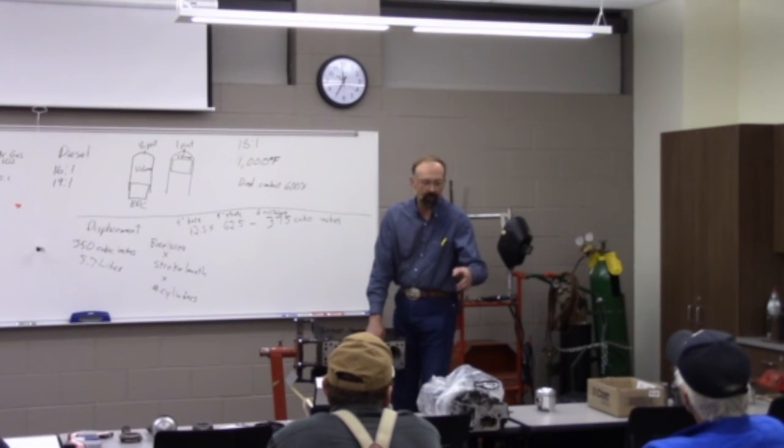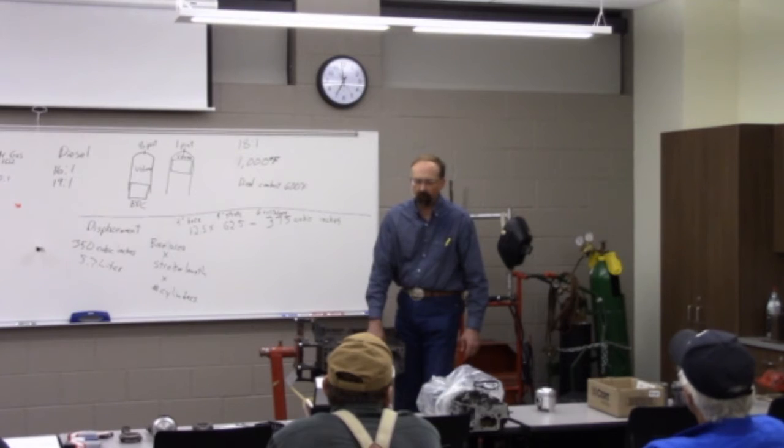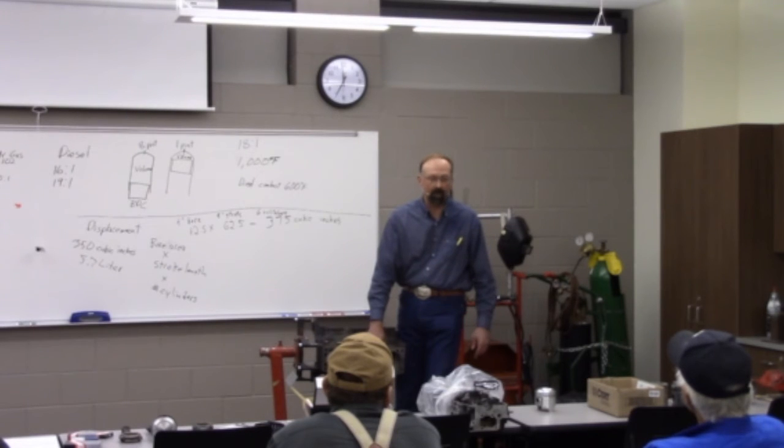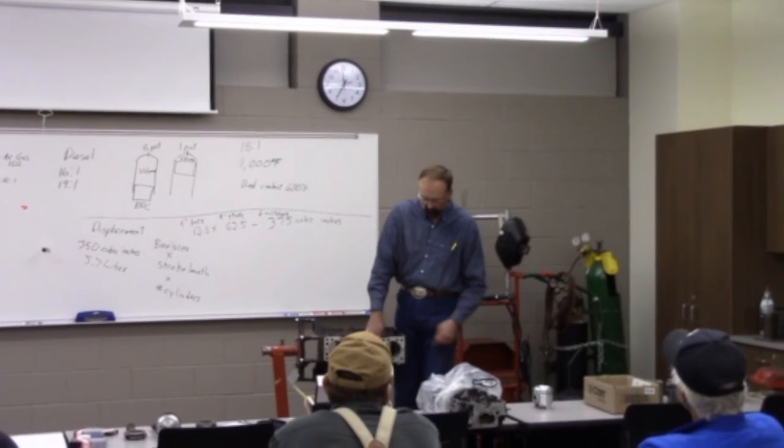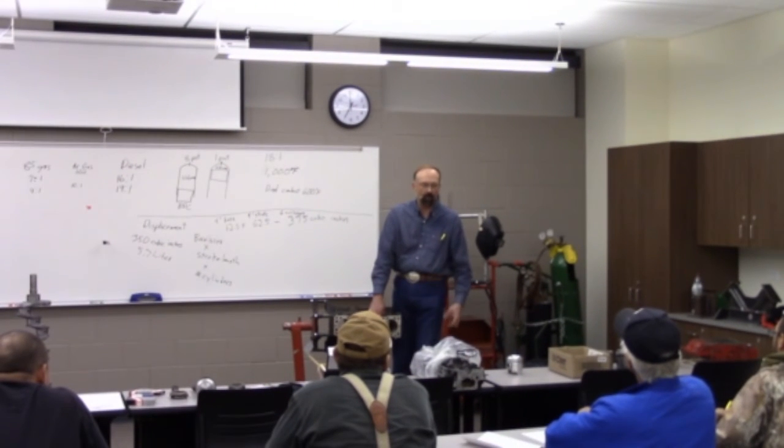And in many cases, the engine parts aftermarket, and in some cases, the manufacturer themselves, for example, that Cummins engine out there, they make pistons in 0.5 millimeter over, in 1 millimeter over, and then the block is not considered junk until there's a defect in the cylinder wall that's more than 2 millimeters over size.